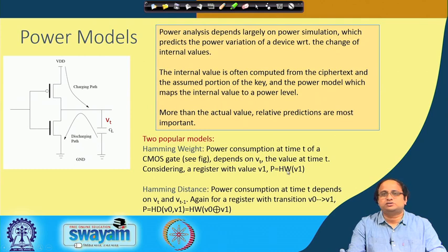Even in other contexts where you are not doing a pre-charge, suppose you are considering a cryptographic circuit. In a cryptographic circuit, often the previous state is randomized, you basically have random data, and in the t-th clock cycle you are doing a computation which is probably dependent upon the key, and you want to sneak out that dependence by using a power attack.